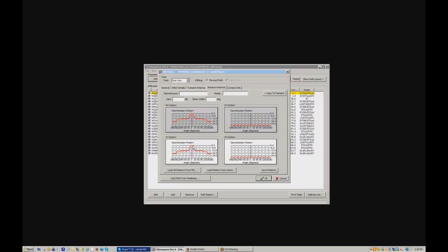So we can do one of two things. We can change the transmit antenna to something with a little narrower bandwidth. This has a bandwidth here of 16 degrees, which is quite wide, and we may be able to reduce the interference caused, or we can go in and change the receiver. Well, that receiver antenna is their antenna, and they might not be too willing to do that.